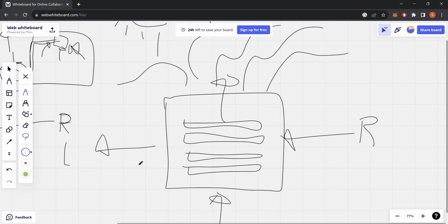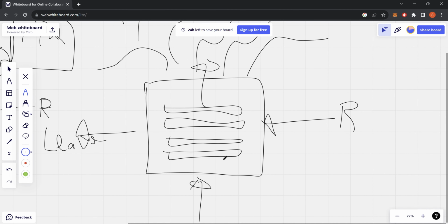It's gonna leave the house. Okay, so that's what's going on in those two. The second thing that's happening at the same time is these coils. So heat moves from hot to cold. In order to get the heat to go from the air to the pipes and then into the refrigerant fluid, you need the refrigerant fluid to be colder than the air.